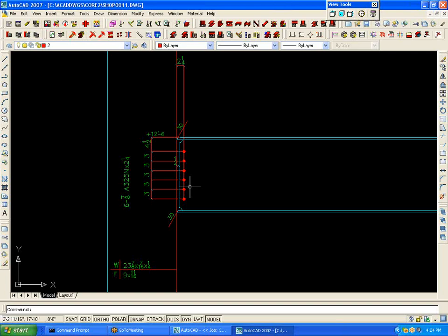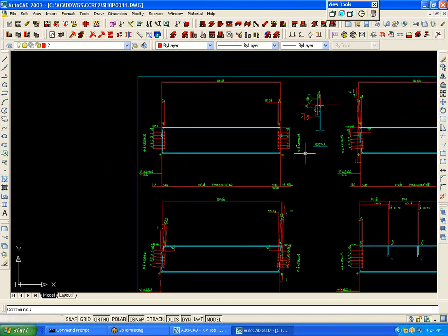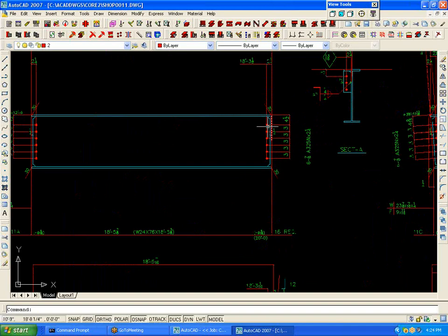It's not rocket science. It's structural steel. So the system knows that and cuts the web back a 1/2 inch so that there's never any conflict with the weld, which is exactly what I would have done by hand. The elevations shown on the beam, everything you need to know is here for the shop and for the checker.